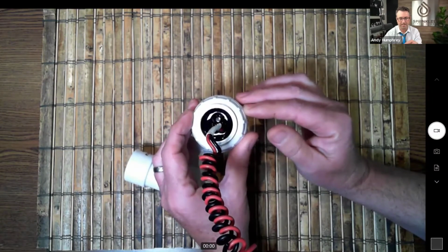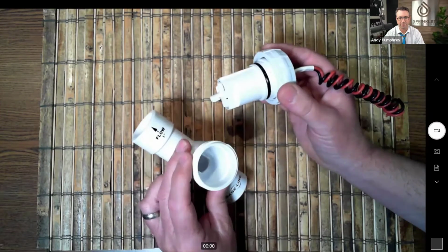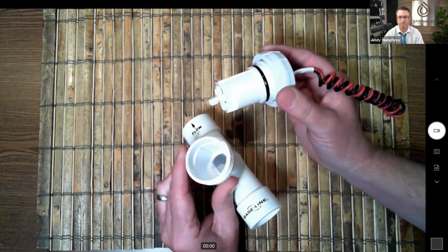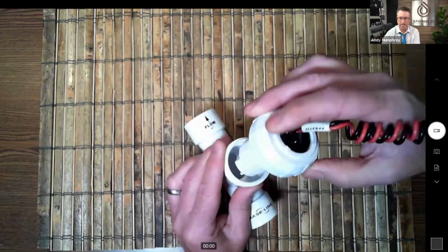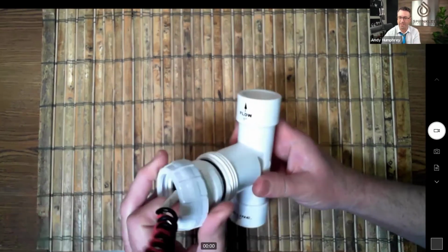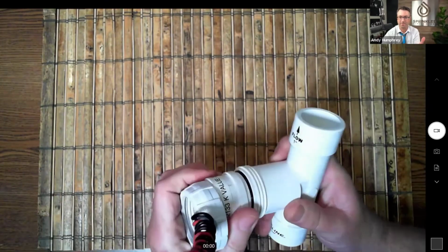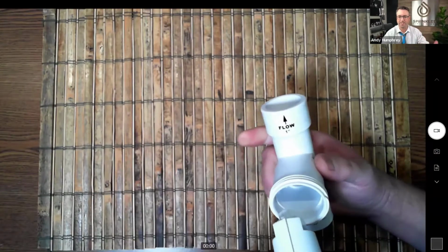And if you look at the side of that insert, there is a rib that lines up with the T. So you can only put it in one exact way. But if you're off a bit, you can kind of jam it in there and screw the lid down. And it was in there just a little bit crooked, where the paddle wheel wasn't able to turn.